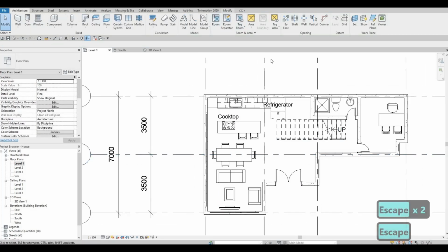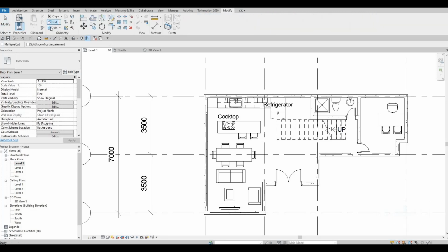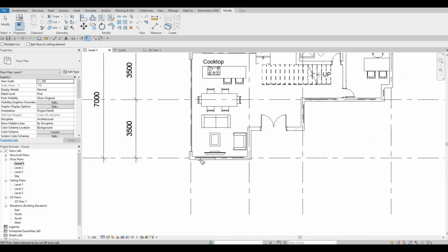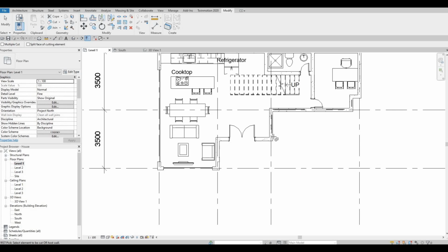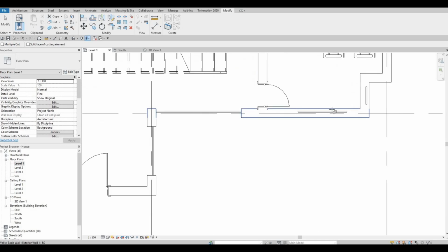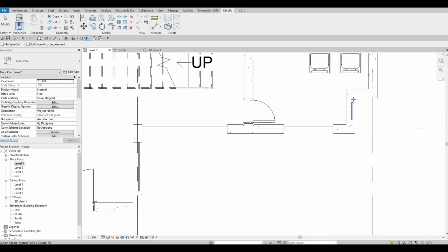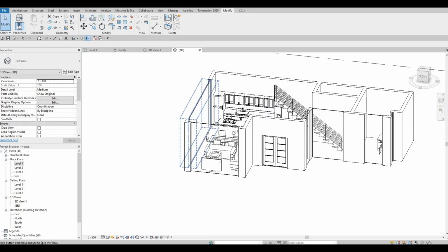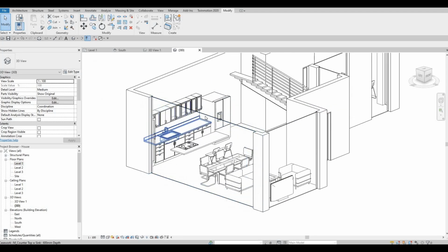And then after that, the error that you're seeing earlier, it's because we haven't cut the geometry yet. So what you have to do is click on cut and then click on the wall first and then the curtain wall. So wall and then curtain wall, wall, curtain wall, wall, curtain wall, like so. And then don't worry about the sizes, as you can change it in 3D as well. As you can see, we can change it like that.